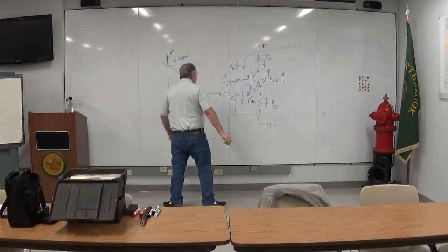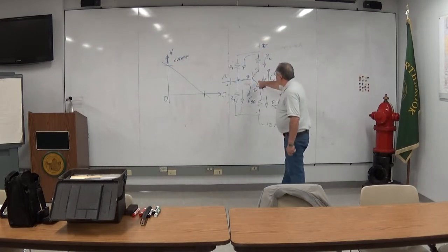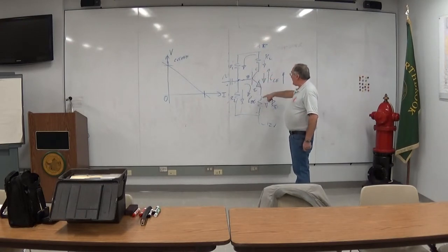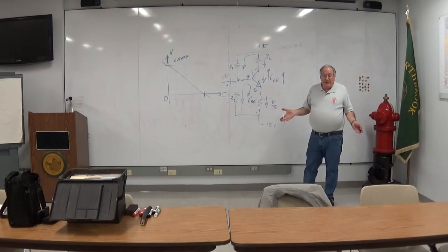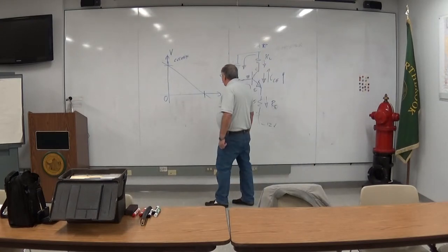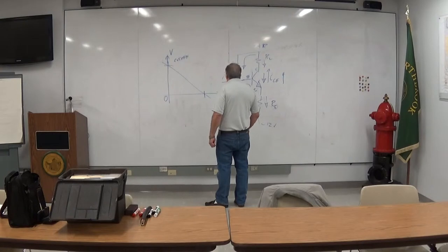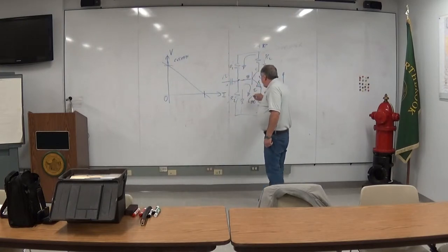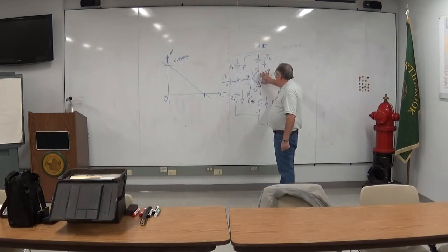Why? Because nothing's flowing through the transistor. If I'm not injecting any minority carriers in the base, I'm not going to get any flow of current from collector to emitter. And this transistor is like a switch. It will be shut off. Nothing will come out. Okay, what if I go the total other direction? I up the current here, and the voltage starts to drop across the collector emitter junction. So more current flows here, more current flows here as a result.